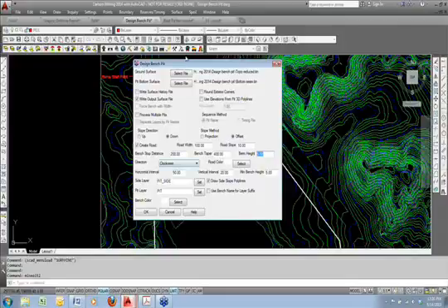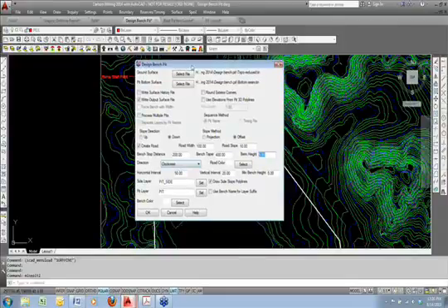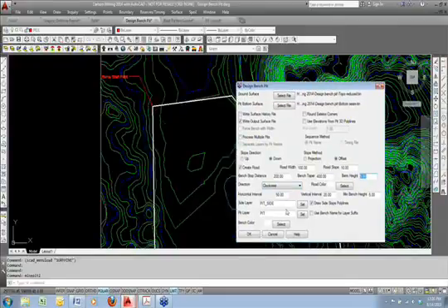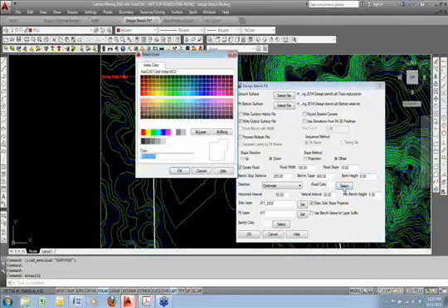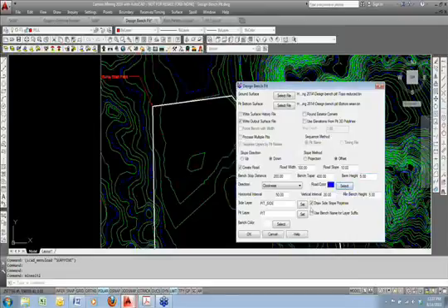Of course, when you're going down and in with the road, you have to choose one direction, either clockwise or counterclockwise, and this time I'll go with the clockwise direction. I'll choose a different color for my ramp or my road. And then it draws the break lines on 2 different layers, pit side and pit. Okay, that's the first page.